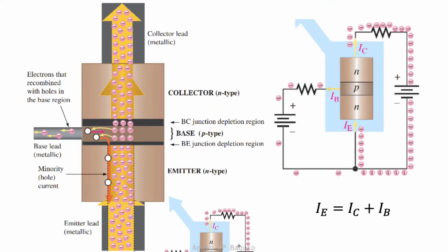As we've previously mentioned, the base terminal is lightly doped. The collector terminal is moderately doped, while the emitter junction is heavily doped. Because of this, the PN junction between the collector and the base has a larger depletion region compared to the depletion region in the PN junction between the emitter and the base. Remember that the PN junction is formed because electrons and holes in the P and N-type regions attract but cannot combine. Because the relative amount of the dopants is smaller between the collector and the base compared to the emitter and the base, the PN junction is therefore thicker.